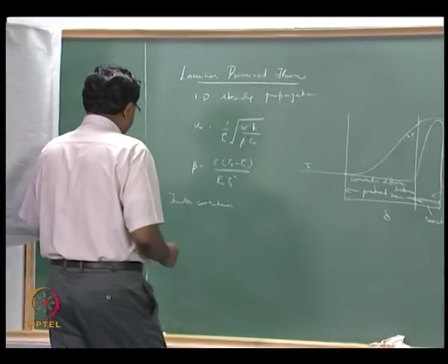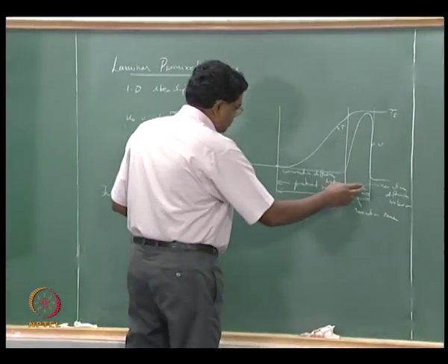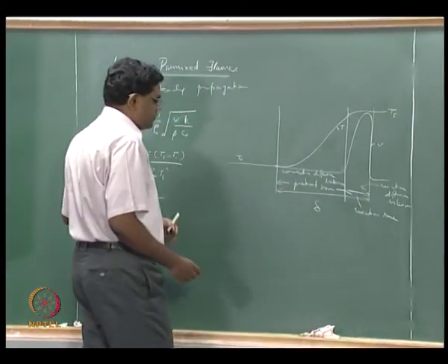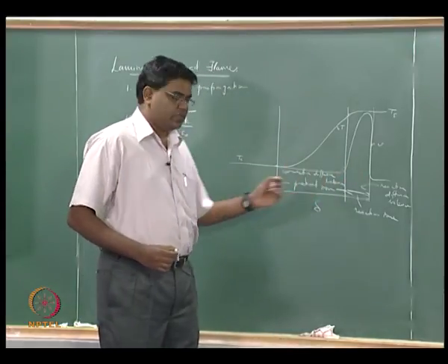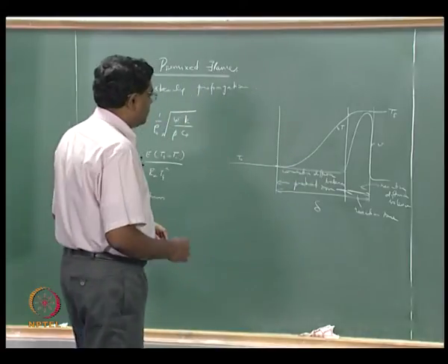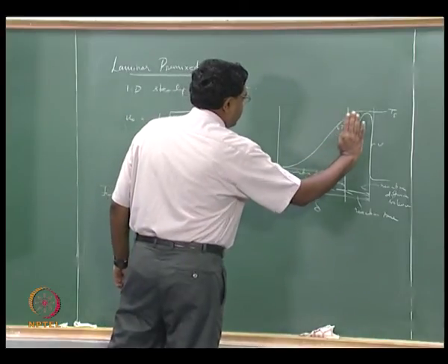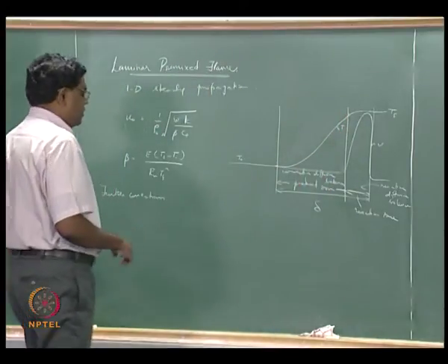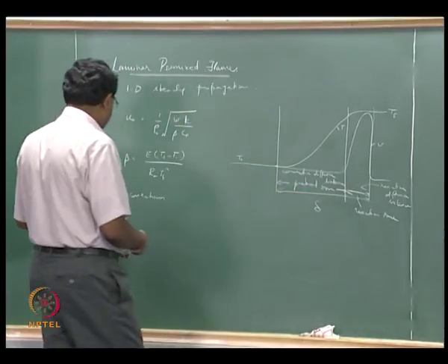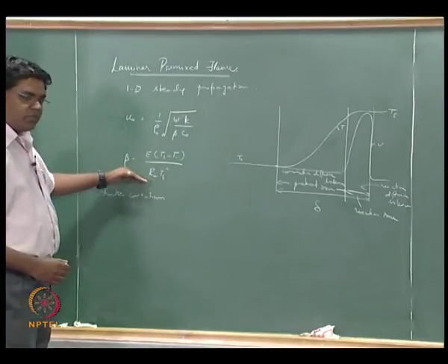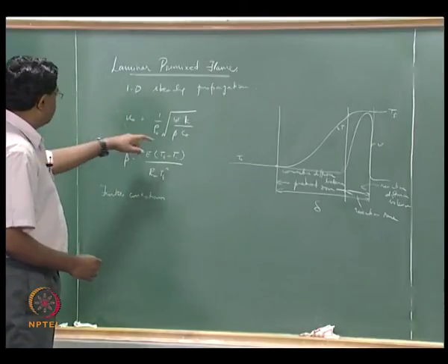So what we found here is that if I now take into account the fact that the reaction zone in this flame thickness is only a fraction of the entire flame thickness, and that is where the reactions are happening, and therefore the heat release rate is going to come from a volume corresponding to only this, and I scale the reaction zone thickness over the flame thickness by a factor given by beta, which is a Zeldovich scaling factor, then I can estimate a u naught which has a 1 over beta term inside the square root.